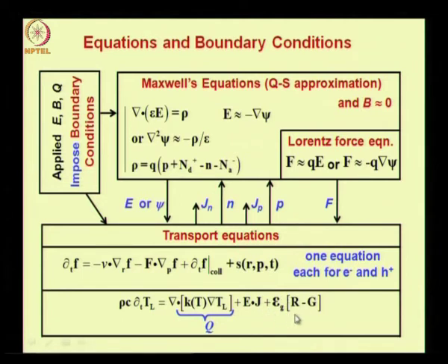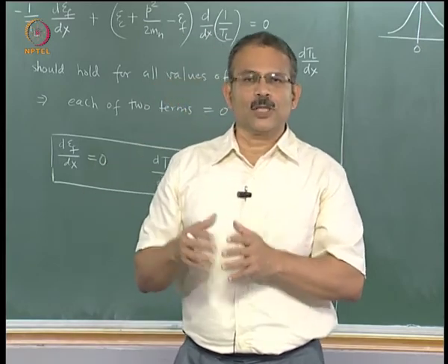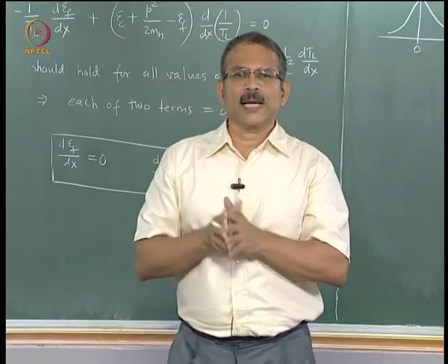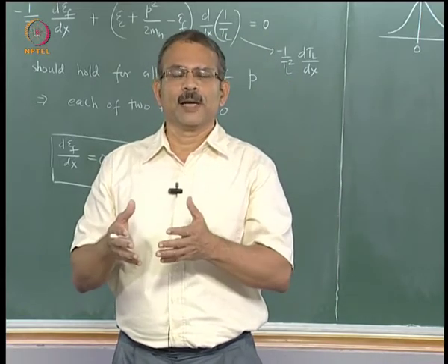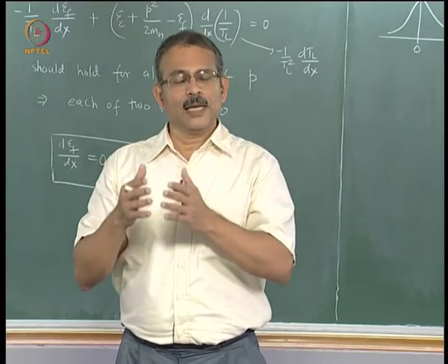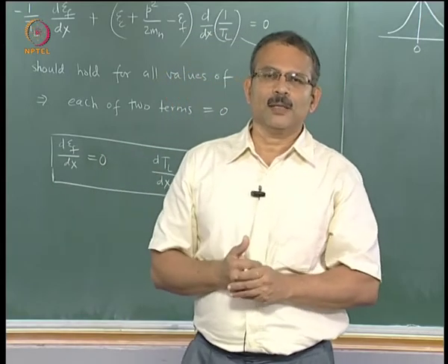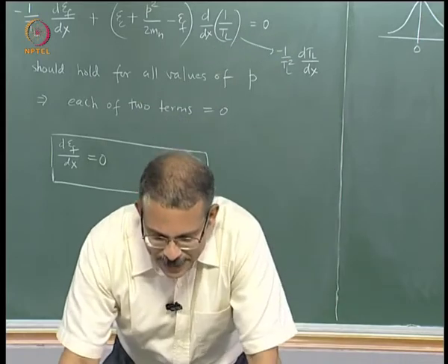Then you can have energy generated because of excess recombination. So R minus G is excess recombination. So you know that if carriers recombine and if the mechanism of carrier recombination involves phonons, then heat will be generated. So we are writing here the recombination mechanisms which result in generation of phonons or heat, in which the energy of recombination is dissipated as heat. Let us take an example of silicon. So you know the recombination energy is mostly dissipated as heat.